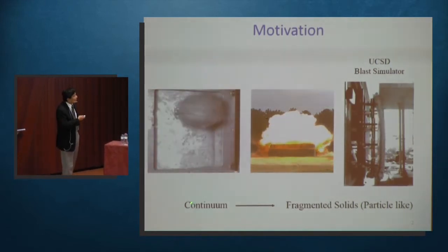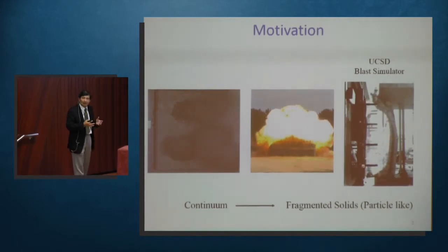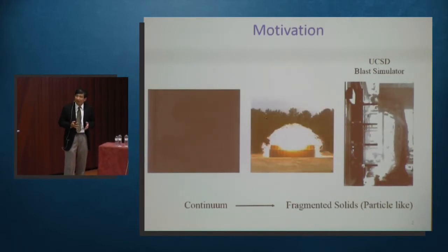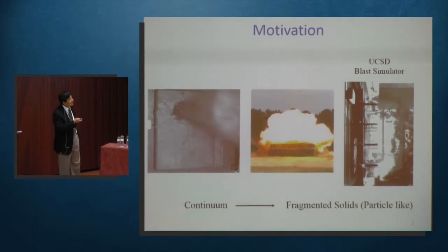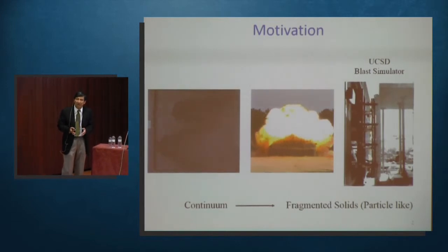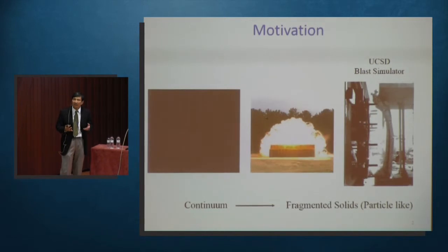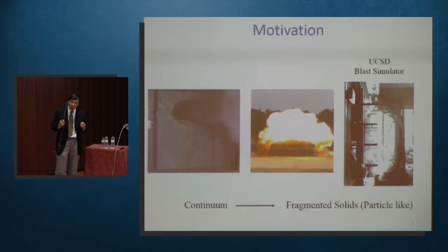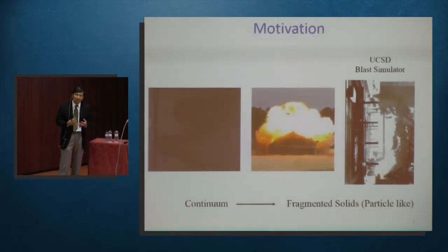And typically, models for continuum systems are like the finite element method or even mesh-free methods. These are really computational methods for continuum systems. Whereas on the other extreme, for particles, as you know, there is another class of computational methods like the discrete element method or molecular dynamics simulation. These are the methods that start with particle models. So what you do is you deal with particle-particle interactions either by kinematics or by potential force functions and things like that.